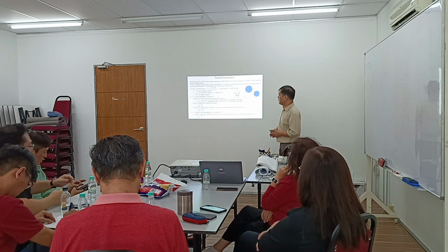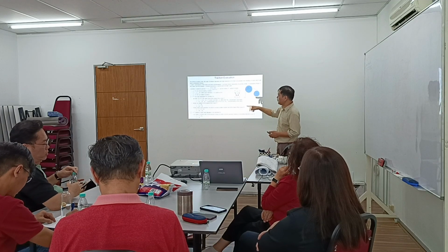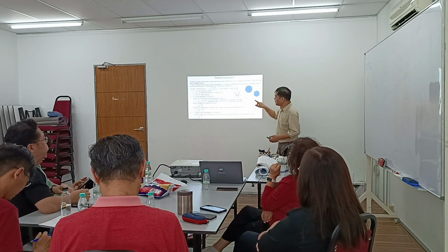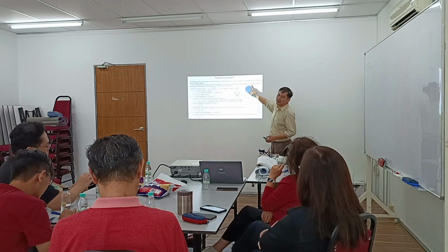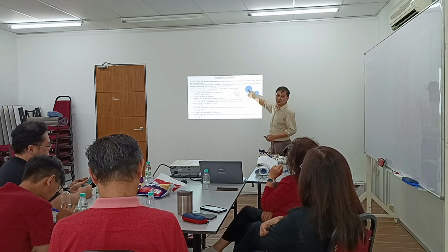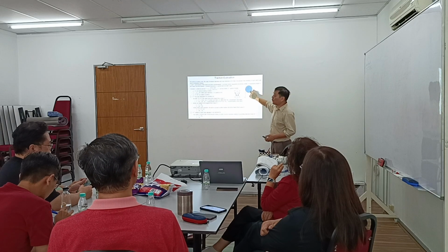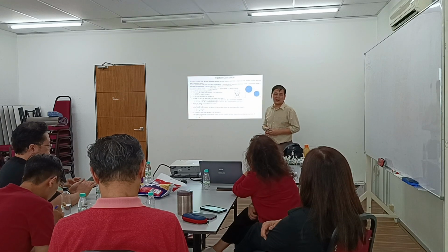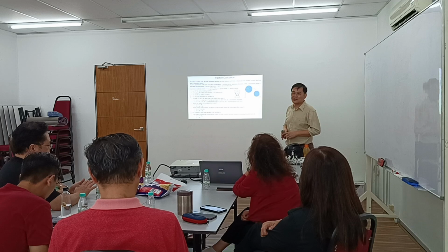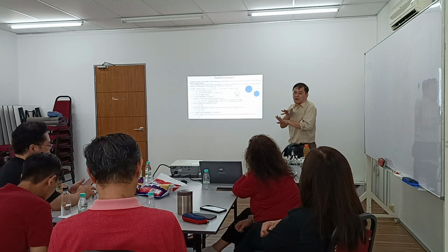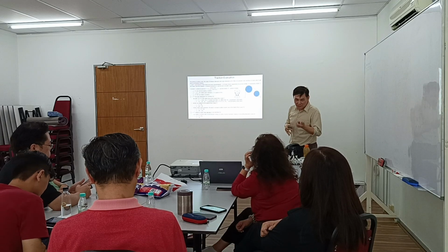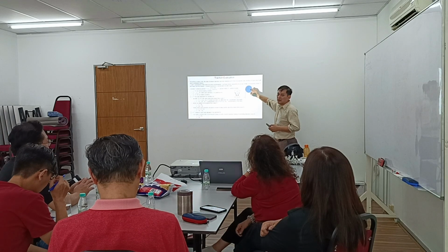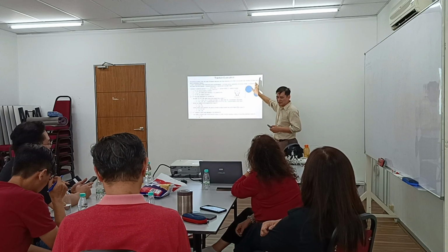As you can see, we have evaluated a certain situation. With this situation, that means T1 over T2 is less than exponential of the friction factor times alpha angle. So that's why this angle is also important. This one we call the wrap angle. Why is this wrap angle important? Because the larger the wrap angle, the more contact surface between the rope and the groove. Correct? So minimally, I think it's around 145 to 160 degrees.